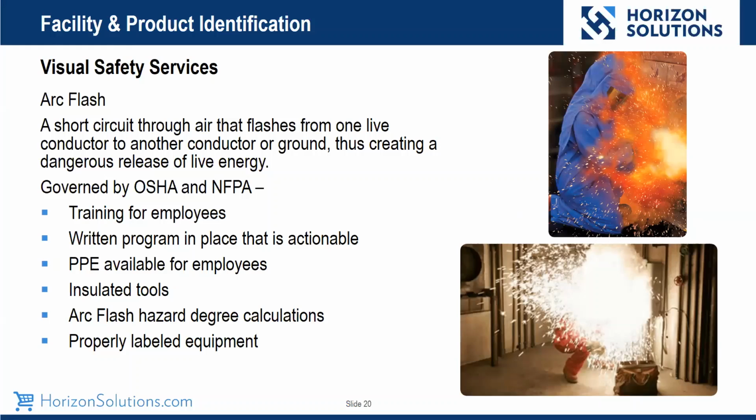Arc flash is currently governed by OSHA and NFPA, National Fire Protection Association, I believe. And what the NFPA is going to look for in an arc flash program is they want to make sure that you all are training your employees. They're looking for a written program that's in place that is actionable. They're looking to make sure that the proper PPE and insulated tools are available. They're looking to make sure that arc flash hazard degree calculations have been performed, and I'll talk about that in just a moment. And then they're looking to make sure that equipment is properly labeled.